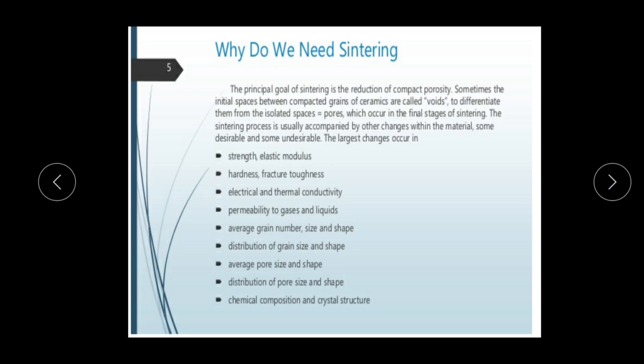Now we will discuss why we need the sintering process. Definitely, dear students, the principal goal of sintering is the reduction of compact porosity. Sometimes the initial spaces between the compacted grains of ceramics are called voids, to differentiate them from the isolated spaces, which means the pores which occur in the final stage of sintering. The sintering process is usually accompanied by other changes within the material, some desirable and some undesirable. The largest changes occur while sintering.